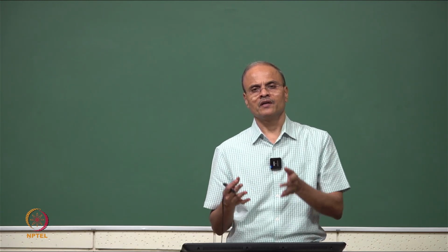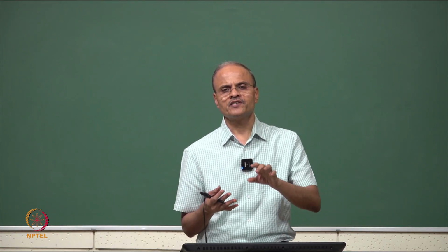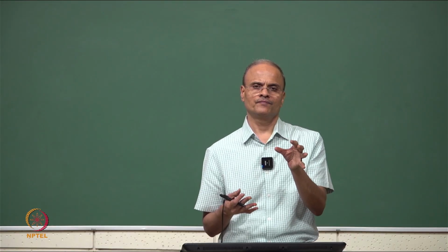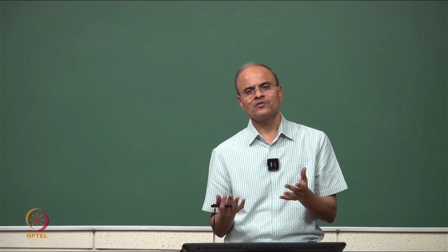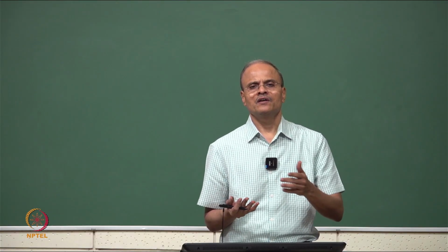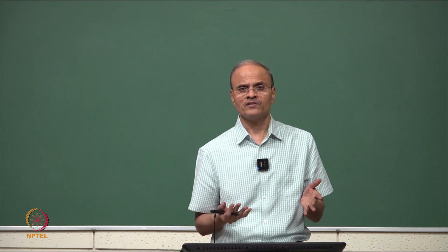So, physical forces F naught minus phi are the actual forces which are acting at different degrees of freedom. But modal force, for example Fr1, represents how much of that physical force vector is exciting mode 1. And in this case we got that as 0, which means that the force vector applied on the system is not exciting mode 1 at all, and hence obviously no modal response in the first mode would be created.